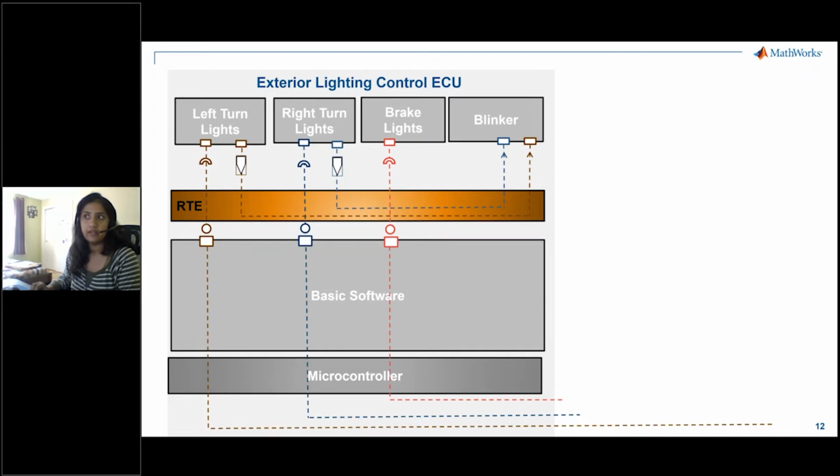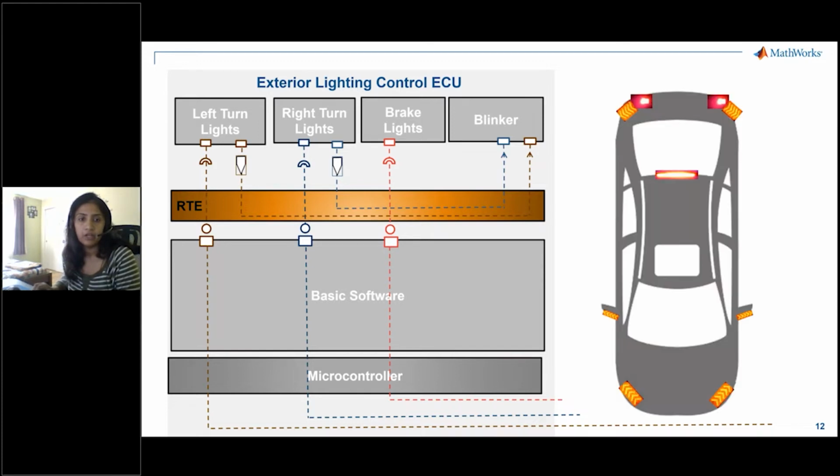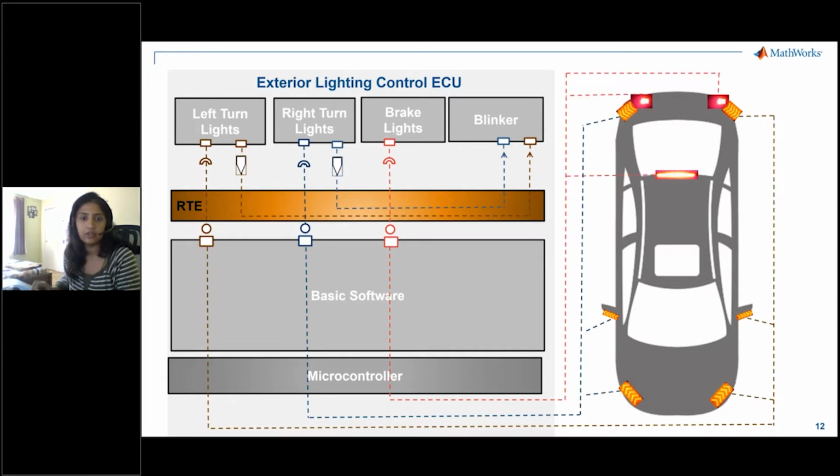And if any diagnostic error occurs, like an overspeed error, then again we will use these client-server type ports. And once the algorithm is processed and a signal has to be sent on or off, it is done via an API that goes via basic software and then connects to a hardware pin and then finally to the actual load on a car. So this is a really high-level example. A lot more technical specification goes into the implementation, but I simplified it to help you understand how the software architecture really works at a high level.